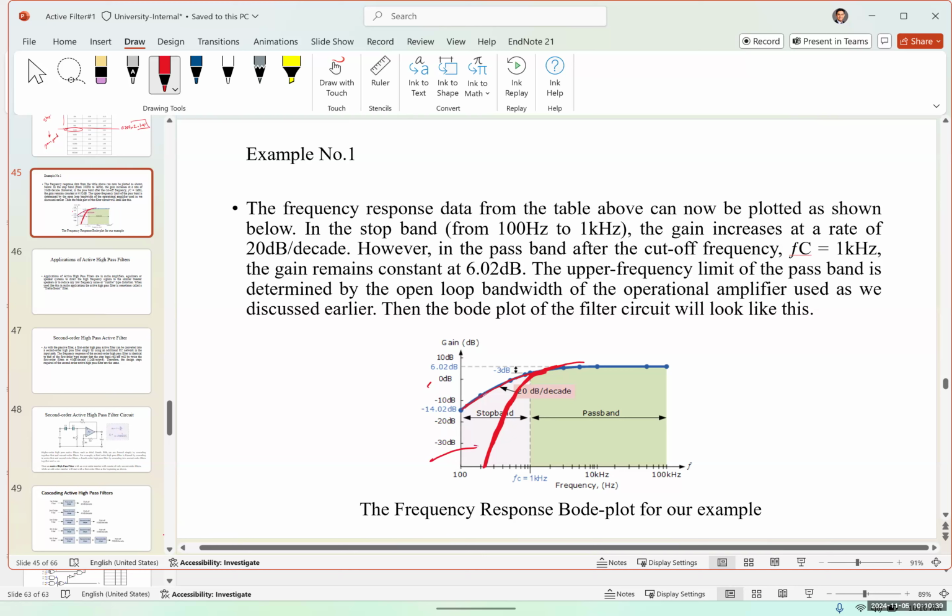So this is a second order high pass filter, or HPF we call it. And this is a first order HPF, or high pass filter. And a third order is going to look like this. 10th order. So the higher the order is, you're going to have a sharper filter, a better filter. Okay. Not going to draw the second, third, and fourth because it's going to confuse you.